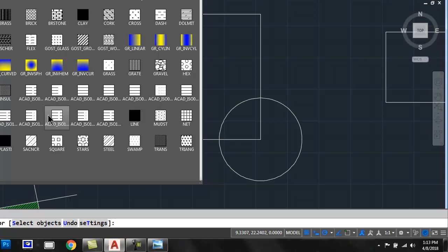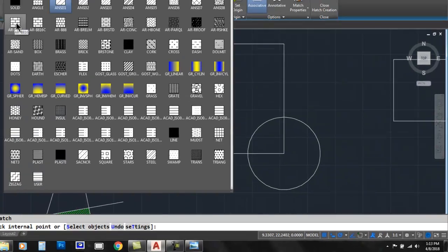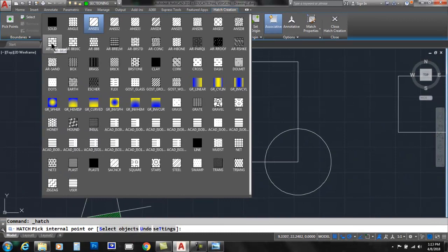Alright, so with that said, let's avoid anything with AR for the moment. For one quick reason, here's AR-B816. The B means block, architectural block, and it's 8 inches tall by 16 inches wide, which is your classic size of a concrete foundation block. So that's what each one of these little blocks measures. So if your drawing isn't even that big, you're not even going to see anything when you click in the area to apply the hatch. So for now, we're going to avoid anything with AR.